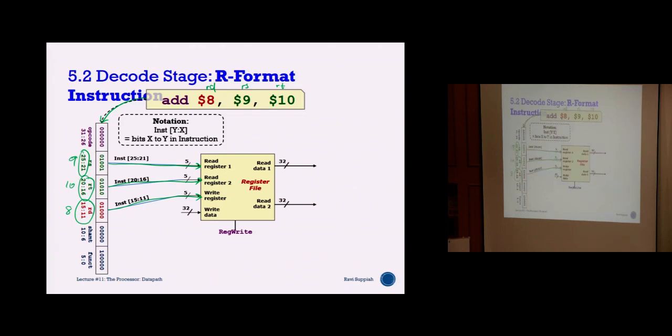So we are trying to understand how your processor is going to take an instruction, and how it is going to use the different bits. We know that every instruction is encoded in 32 bits. How am I going to make use of the 32 bits to tell the processor what to do, where the data is, what operation to complete, and where to store the result? So I need to tell the processor all this information, correct?